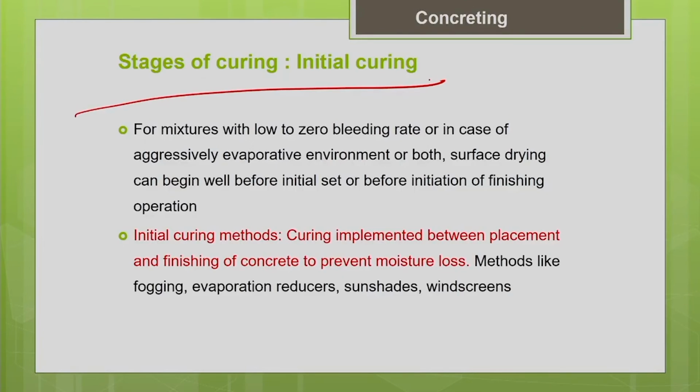For such mixes, obviously, before finishing of the concrete, I cannot apply water as my curing method, because supplying water for curing itself will damage your concrete. Before the concrete attains its final set, if you try to supply water to the concrete for curing, that will damage it. That is why we need some other form of curing, which is called initial curing.